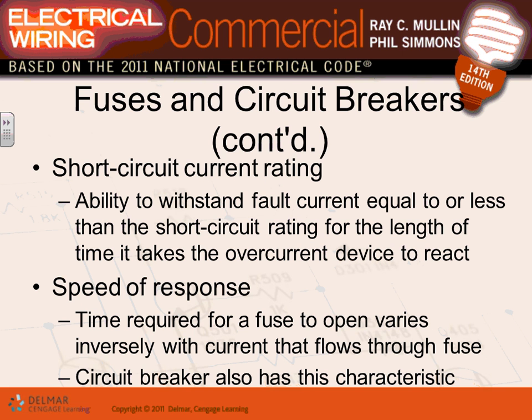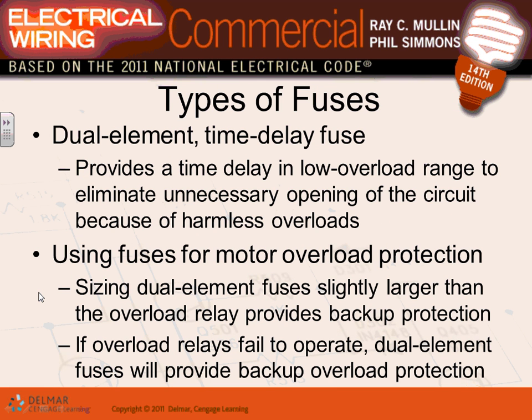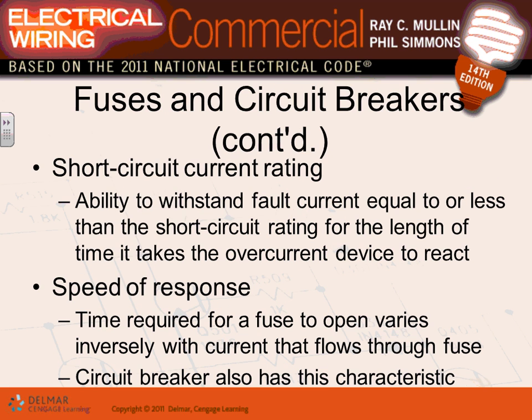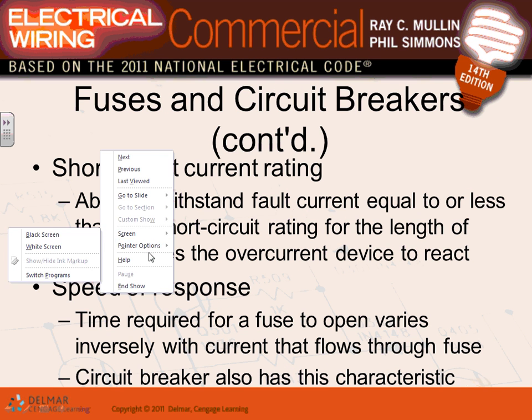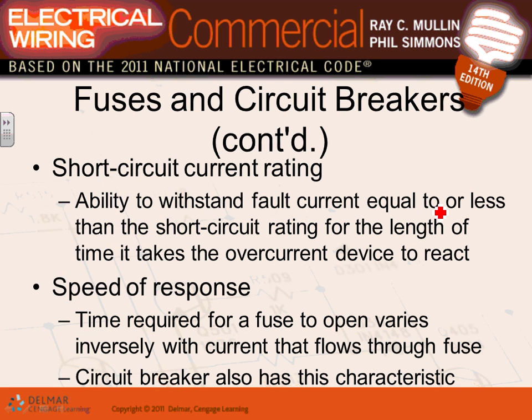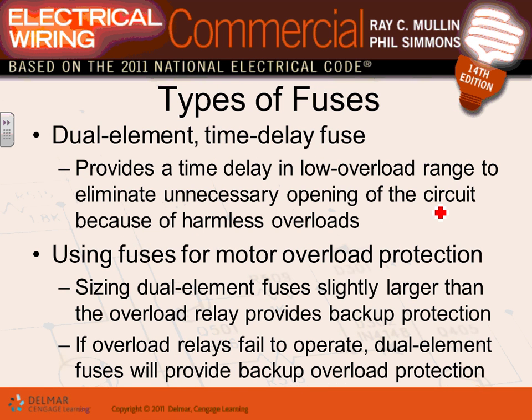Speed of response. When you have a circuit breaker or a fuse, the higher the short circuit, the faster the fuse will trip, and you're going to see this in less than a second here. Same thing for fuses or circuit breakers. It will open faster if the short circuit goes higher.